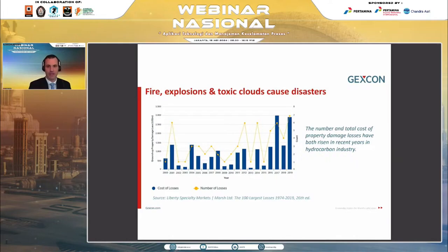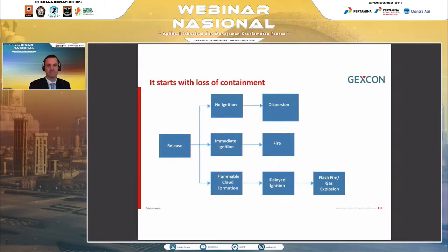Yikes. Hopefully this is coming through for you guys. This one was far more significant, at a pressure of 2 bar. That's 100 times higher pressure than the first case. So, the same volume, the same blockage ratio, and the same fuel. The only difference was the obstacle diameter, but it resulted in 100 times higher explosion pressure. This difference is something that only CFD tools can accurately predict.